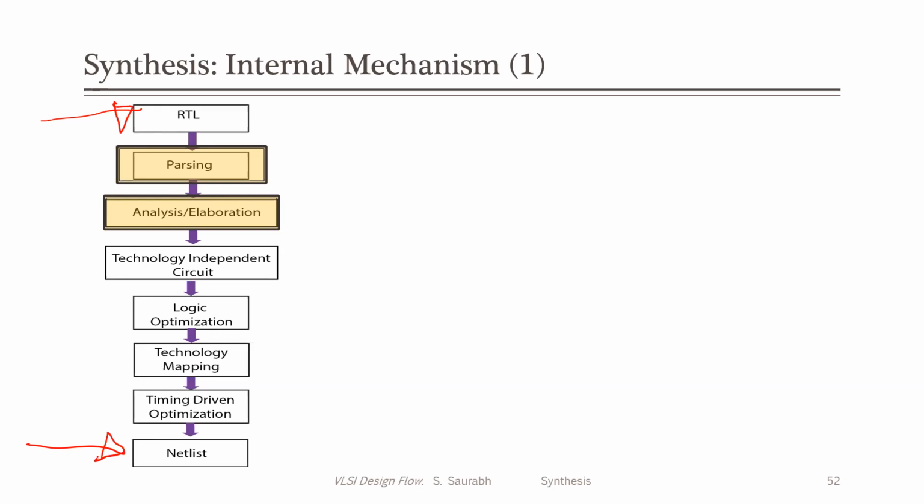So these are the steps that are done internally. The RTL you take, then it is parsed, then analysis and elaboration is done, then a technology independent circuit is created, then logic optimization is done, and technology mapping is done, and timing driven optimization is done.